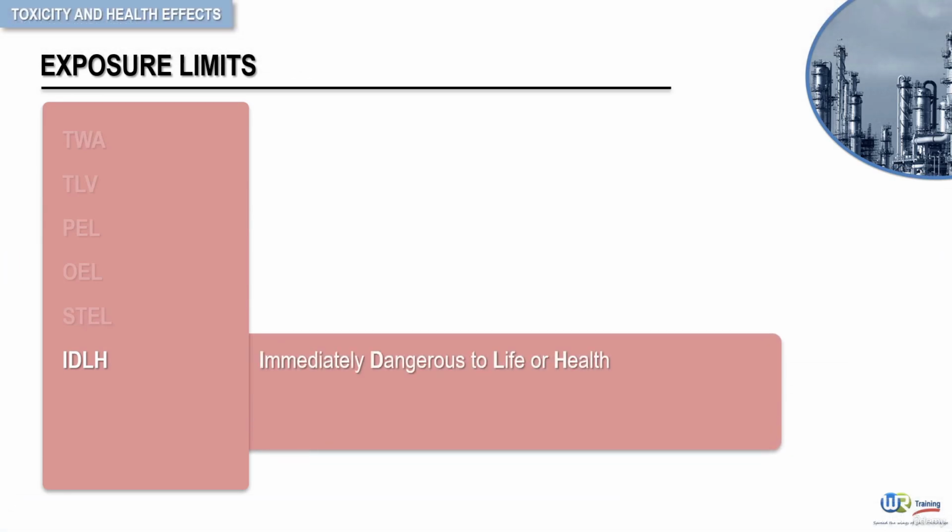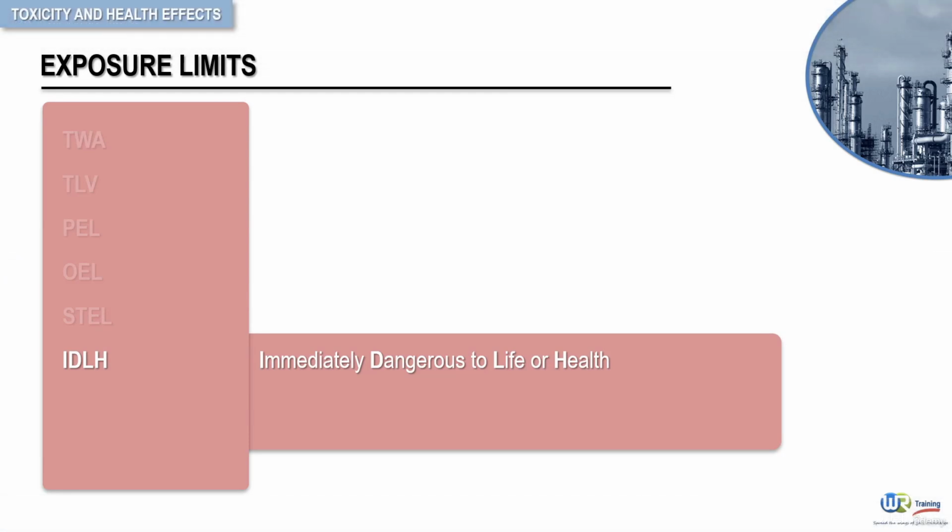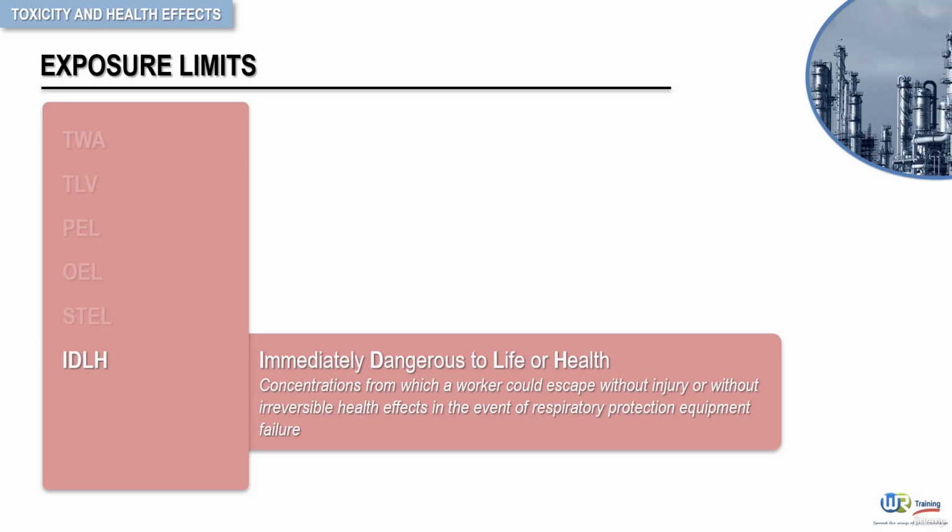Lastly, IDLH, or immediately dangerous to life or health concentrations, are concentrations from which a worker could escape without injury or without irreversible health effects in the event of respiratory protection equipment failure. Only highly reliable respirators are to be used at concentrations above IDLH.